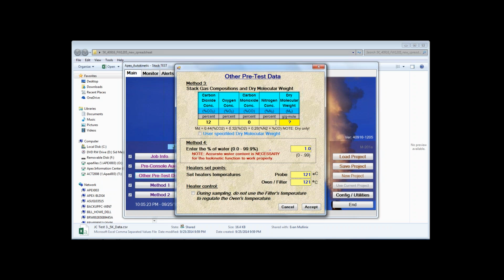So 1981. Okay, 30. On 201A the composition is critical, so you actually have to enter the specific makeup of your stack gases. Moisture in the meter or moisture in the stack stays the same. All your temperatures stay the same.